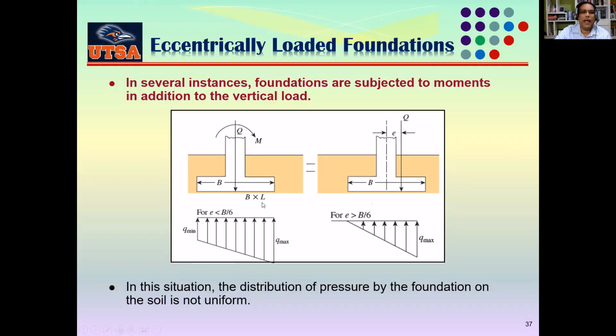Now let me share my screen with you. You can see here that this is our foundation, and there is a load here, and there is also a moment here. The equivalent system, we can just draw, is that the load is working a little bit away from the center of that foundation. So this one is creating a moment. What is that moment? That is Q multiplied by E.